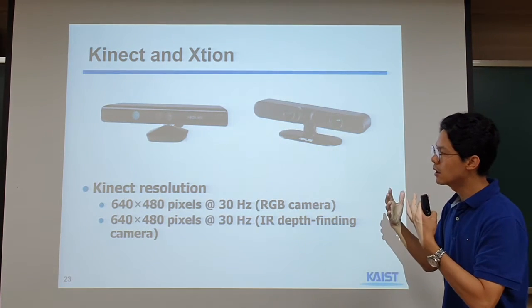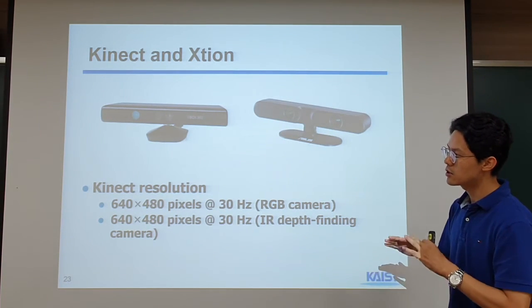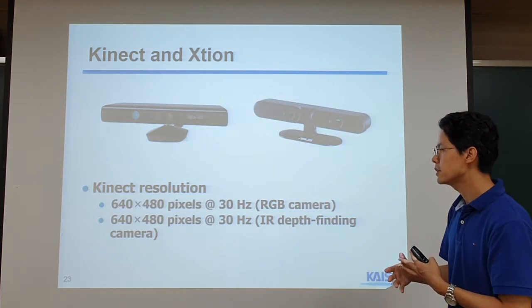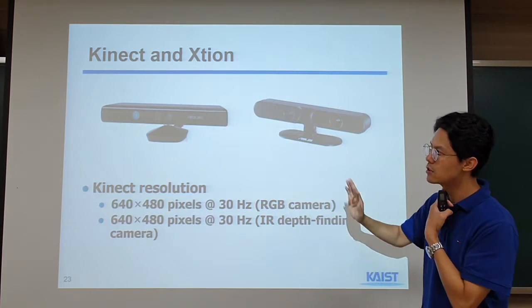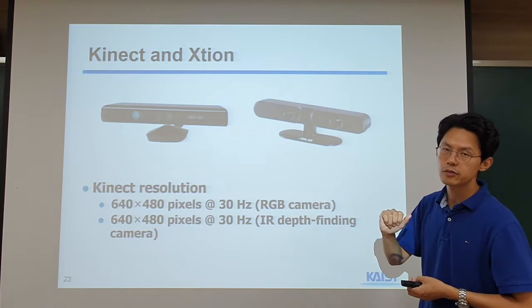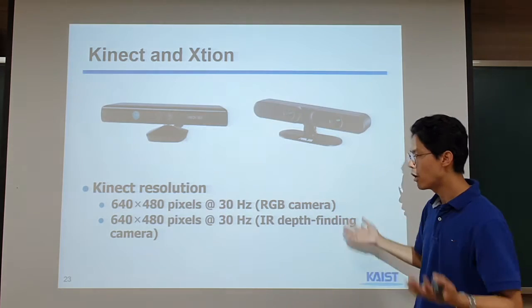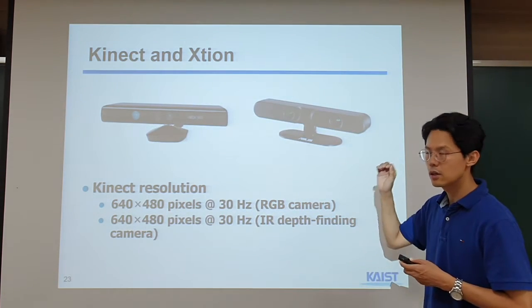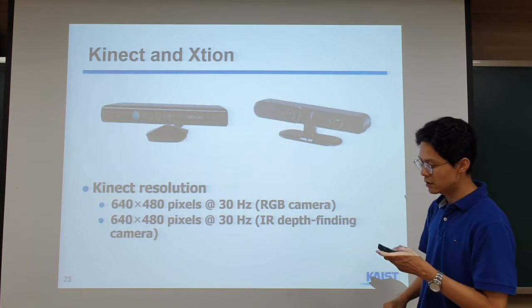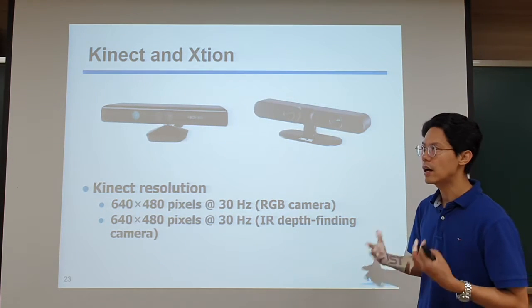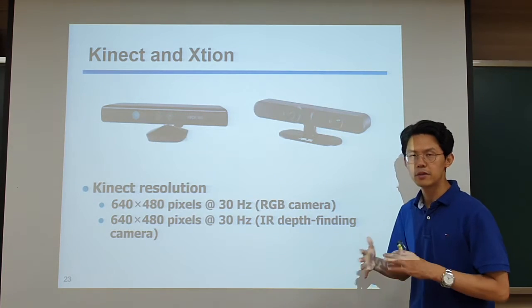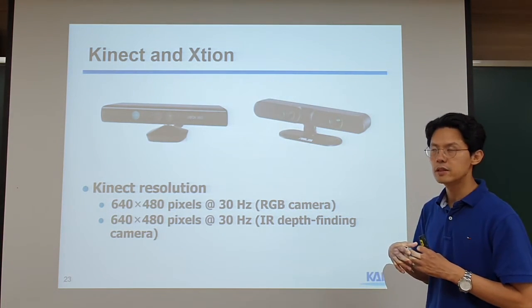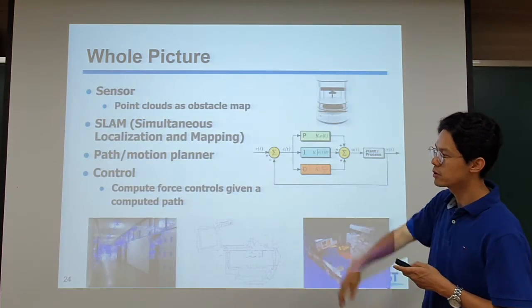And then there are a lot of libraries to handle points. If we process those kinds of point clouds, we can even get triangle and polygon shapes of our robot and also the environment. But right now, in a lot of cases people work directly on the point cloud. Even though I explained a lot of motion planning techniques based on triangles, virtually all of the digital motion planning techniques naturally work on this kind of point cloud.